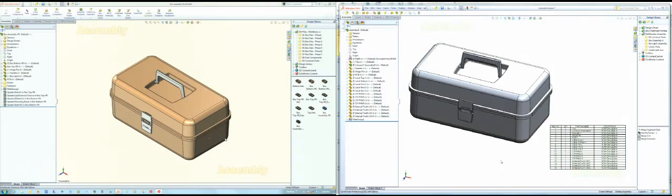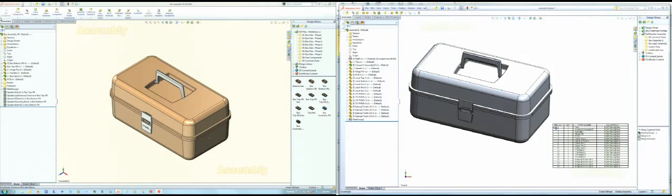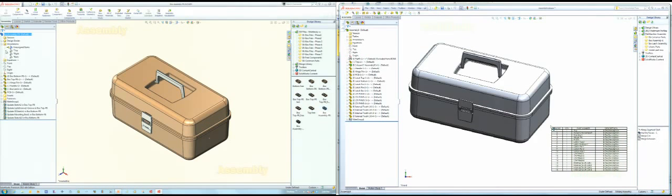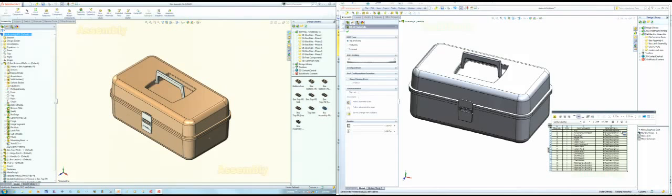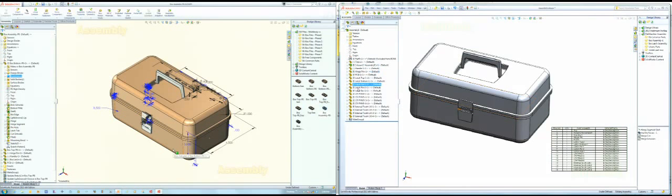Okay, so you end up with this. Now, once we do that, we can make a real bill of materials. And it's going to go just like, the part number is going to be the file name, and the description is going to be a custom property you add to each of the part files. So now we've kind of taken all those multiple bodies and we've pushed them out into the assembly, and it's used a bunch of fixed relationships, okay? But you don't have to keep those fixed relationships.